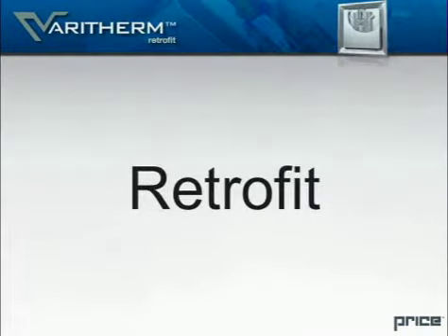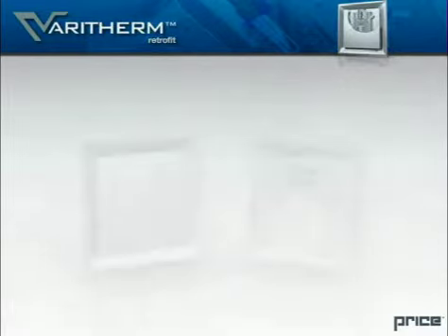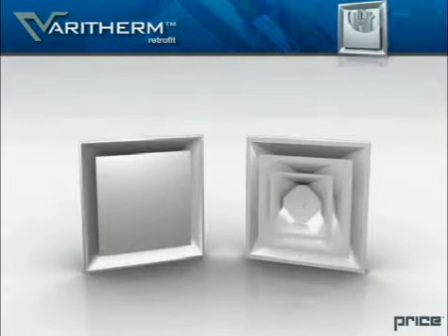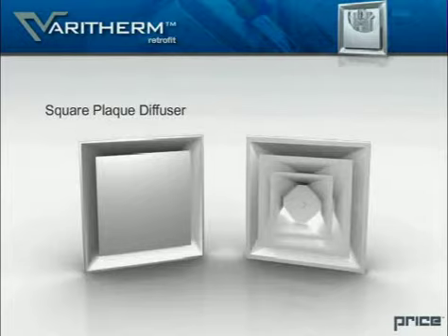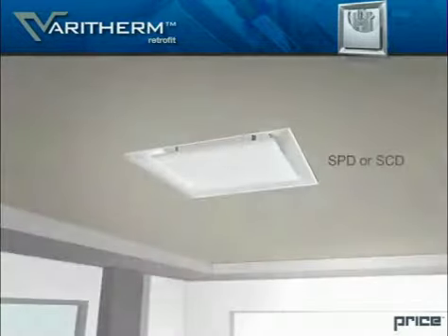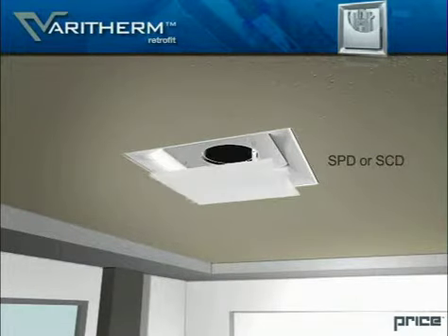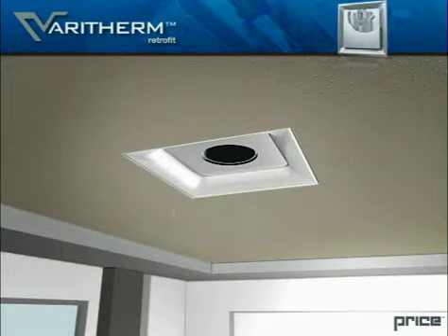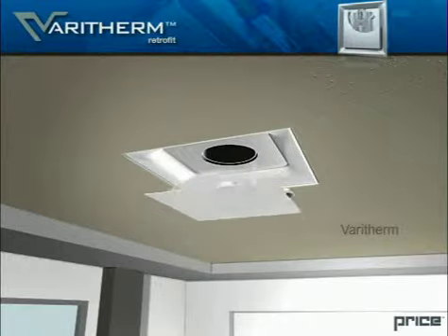Retrofit. To help with trouble zones, the Varitherm is also available as a retrofit of our popular square plaque diffuser or square cone diffuser found in buildings across the continent. The Varitherm control module simply replaces the SPD or SCD core without the need to replace the back pan.